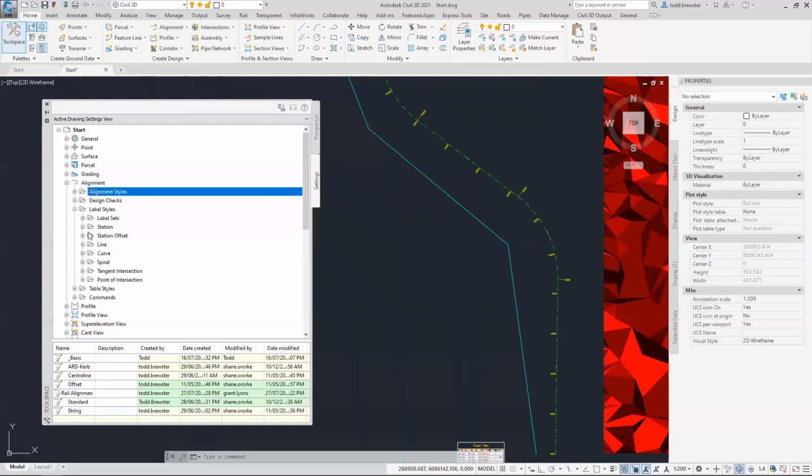When it comes to the chainage markers, there are actually 8 different chainage types that can be labeled on the alignment. The most common one you're probably familiar with would be major, maybe the minor, and the geometry points. The others are derived from other elements of the alignment and other properties. A combination of these together is what's called a label set, which is this piece that sits at the top. So that you don't have to define what it looks like for every subcomponent, you can label up an alignment based on a set of predetermined label types and frequencies.